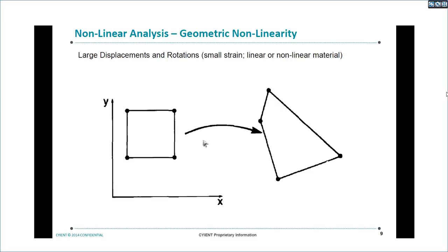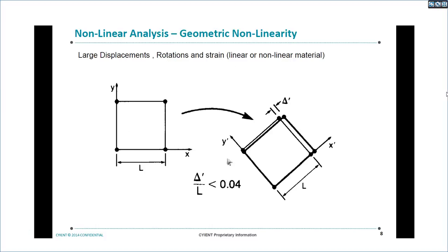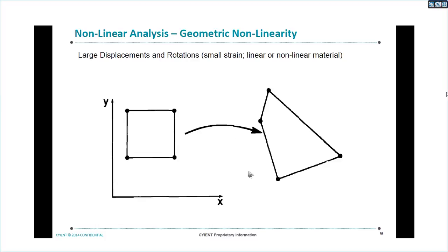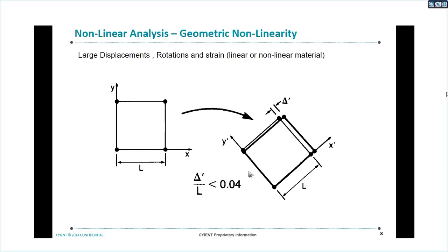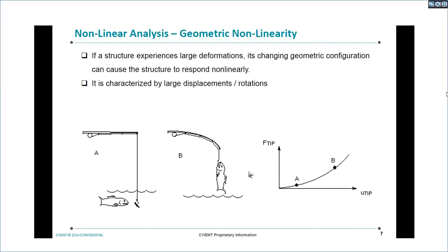This comes under large displacements and rotation geometric nonlinearity. So this is under small strain, and this is under rotations. So this we have discussed. So here in geometric nonlinearity, one of the important things is that the stiffness matrix is nonlinear. Okay. This is purely because of geometry.